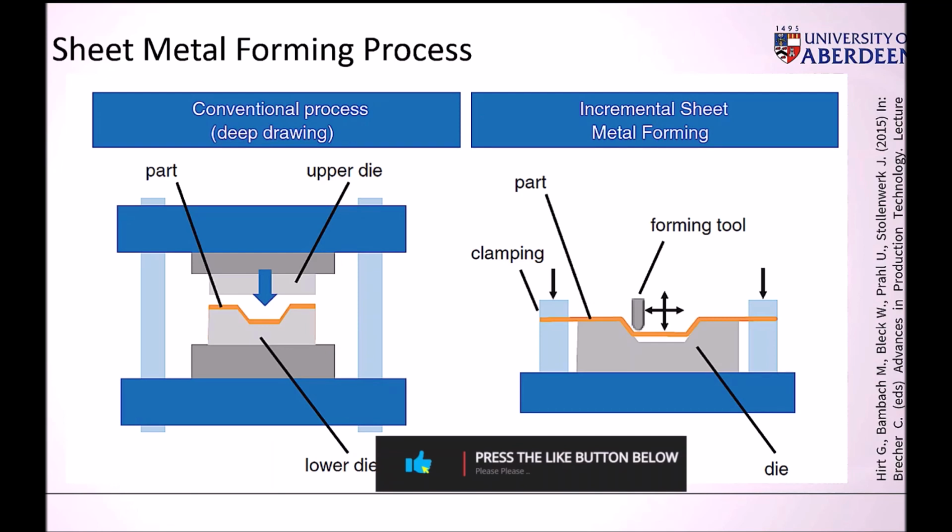We have been working on it for over 10 years now. If you talk about our models, our crystal plasticity based models can take into account face-centered cubic crystals, which is aluminium. We talked about aluminium, which has face-centered cubic crystals. You can have body-centered cubic crystals or hexagonal close-packed crystals as well, depending on your microstructure. So for example, titanium, if it's dual phase, you can have BCC and HCP as well, right?